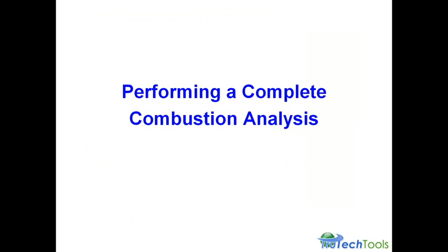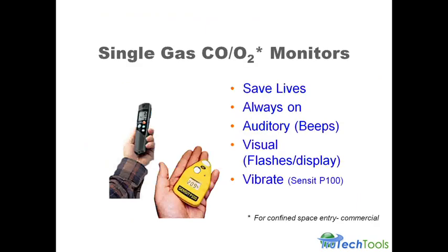All right, so let's walk through the steps to perform a complete combustion analysis. First of all, you should always carry a single gas CO monitor because there's a high probability at some point in your career this thing will save your life, because you don't know when you're walking into a home, a business, a boiler room, anything else with CO. I particularly like, we sell the Testo and the Sensit P100. I particularly like the Sensit just because it's auditory. It beeps, it vibrates, and it's got a flashing light on it, as well as a display.